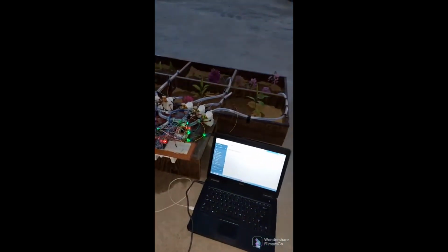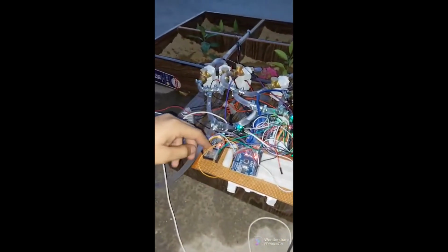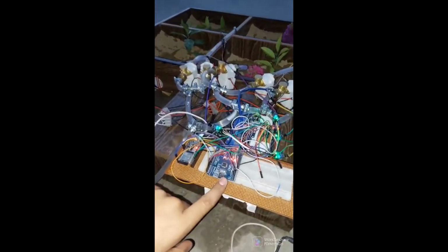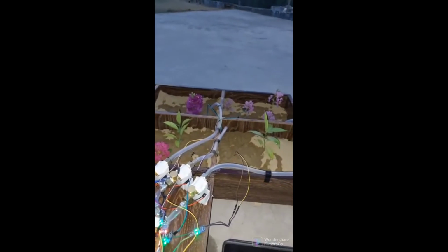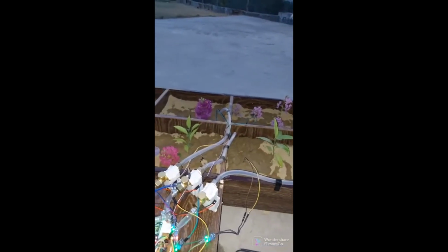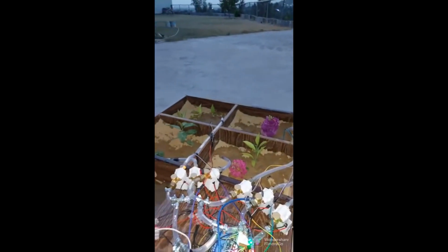Arduino takes values from the sensors and communicates with ESP32 through the TX and RX pins, transferring the values to ESP32, and ESP32 collectively sends 6 moisture sensor values to Firebase. When the moisture is less than 50%, our water pumps and valves are on, and when it is greater than 50%, our electric valves are off.